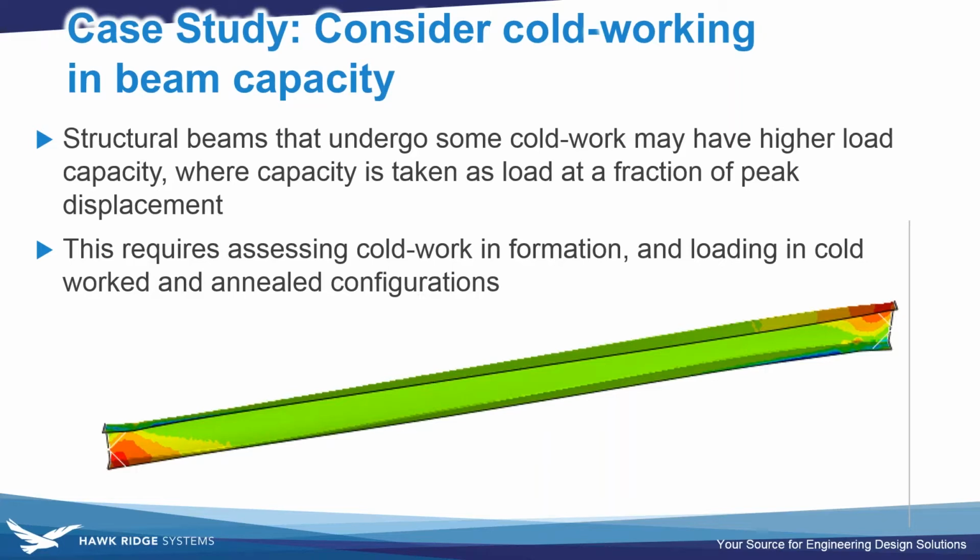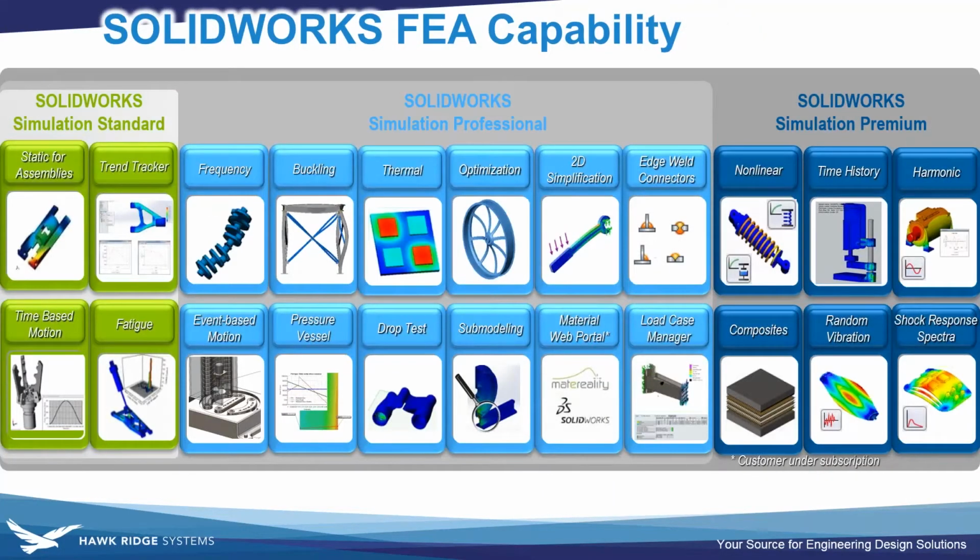And so at a minimum, if you wanted to approach this type of manufacturing problem, and most likely any type of manufacturing problem, because it involves permanent deformation to a material, you're likely going to need what we call a nonlinear study, which is part of SOLIDWORKS Simulation Premium. That's the top-end SOLIDWORKS simulation package if we're talking about FEA tools.